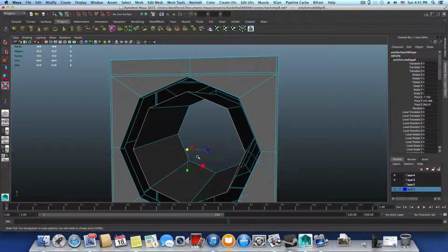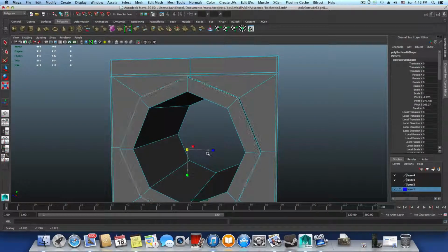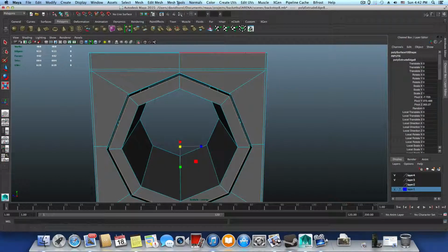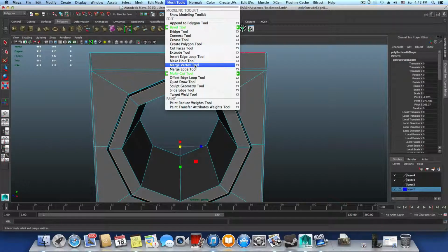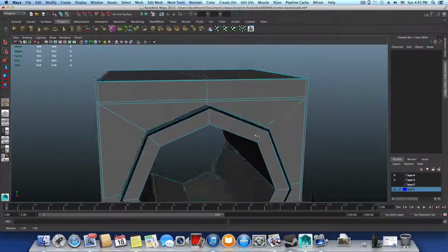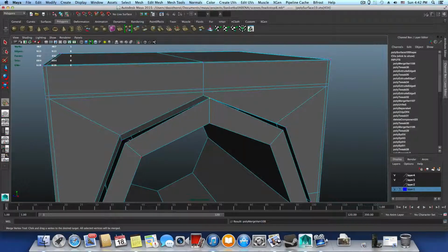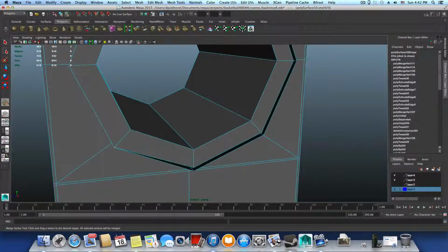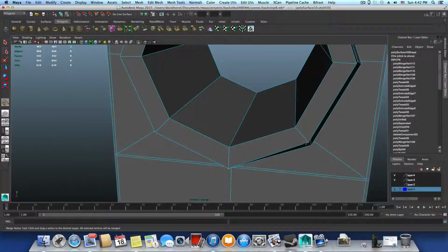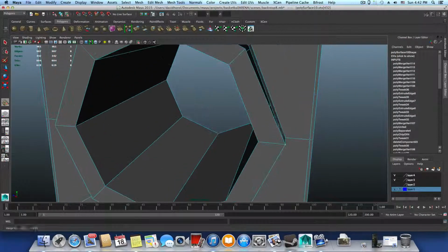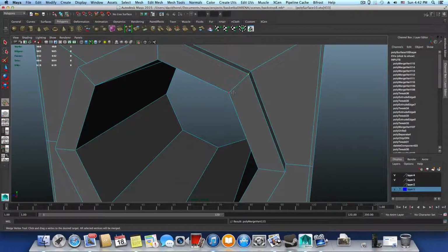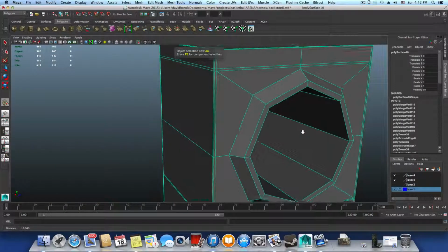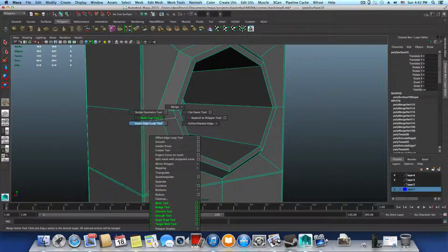Now with that, I can extrude it, switch to scale tool, and do something like so. Okay, I won't close this. I want it to be a little bit open so I can obtain those vertices, and switch to merge vertex tool and do something like so. So I'm patching them over here, and that's all good. That way. Nice. Okay.